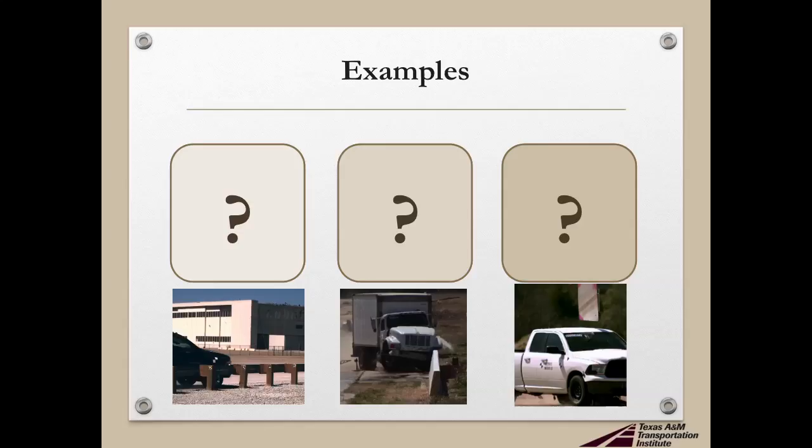But what does that overall mean to the benefits that we'll derive from this document, the safety improvements that we'll realize? Well, I thought I would do that through 3 illustrative examples here. So the first example we're going to talk about is what I would call a standard W-beam guardrail under MASH test level 3 conditions. That's the basic test level for high-speed roadways.